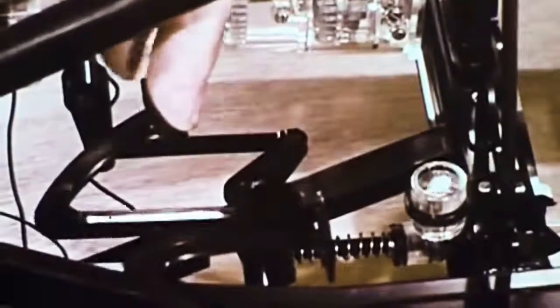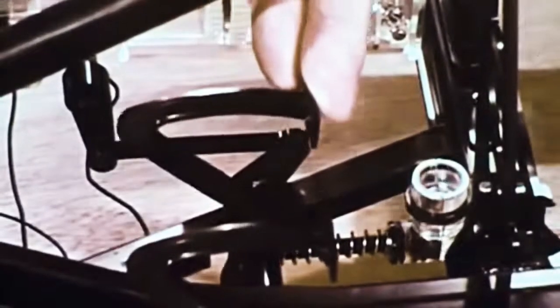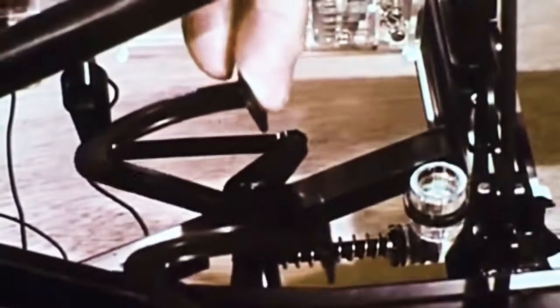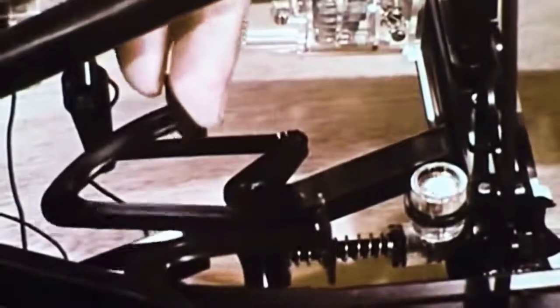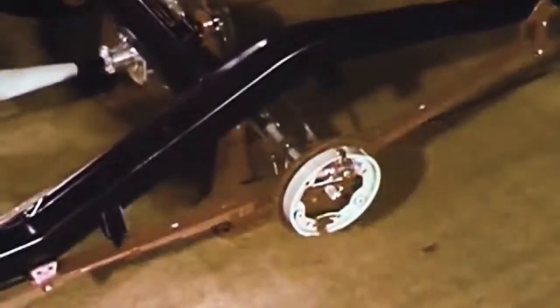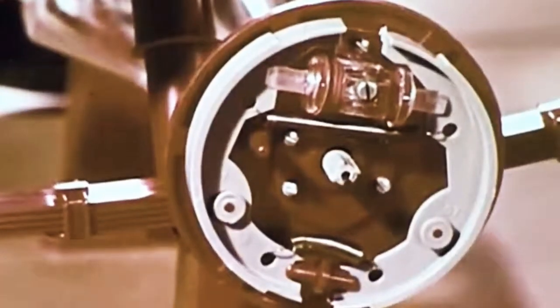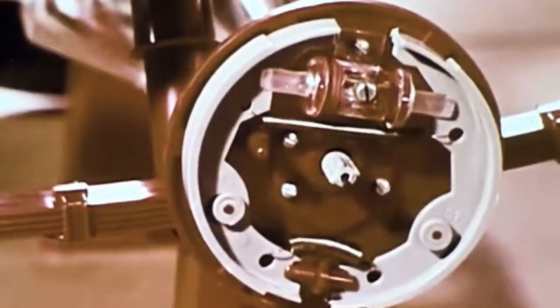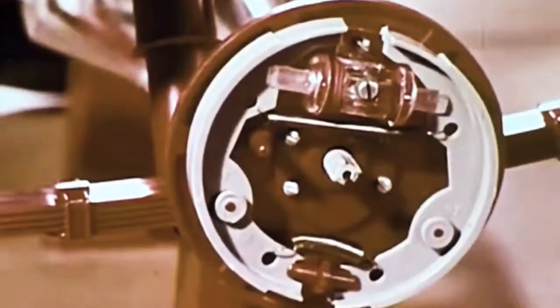Here is a model of the brake system using water as the hydraulic fluid for this demonstration. The hydraulic system tends to equalize the braking force between the 4 wheels and multiplies the pressure of the driver's foot for easy braking. A very small amount of travel is needed to bring the brake shoe into contact with the brake drum.